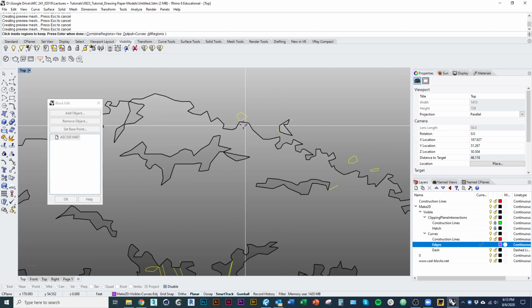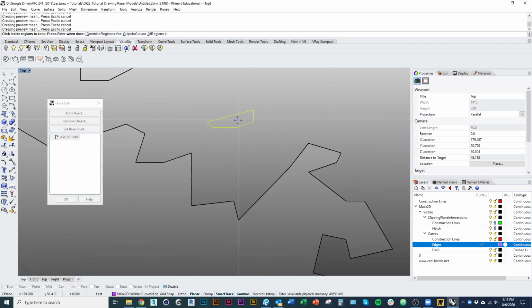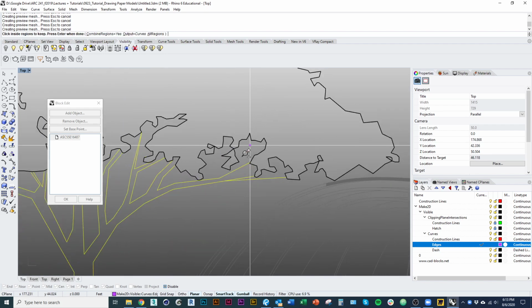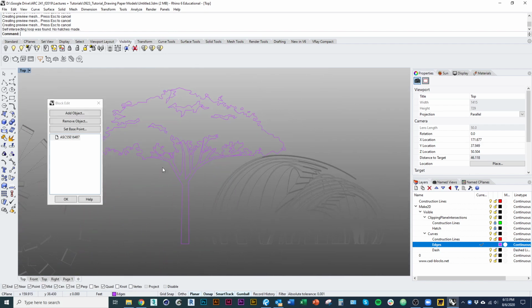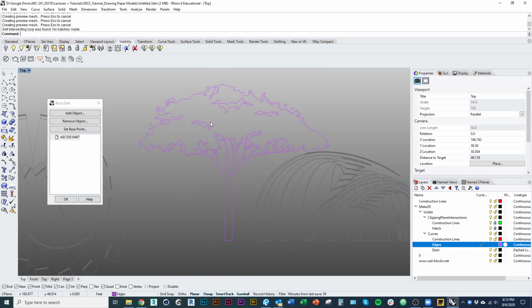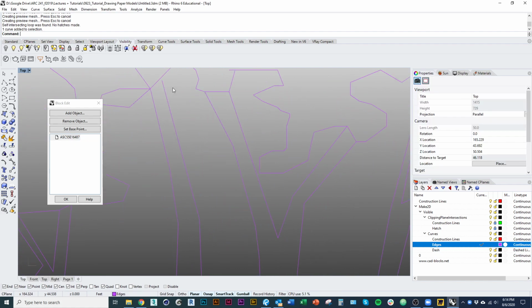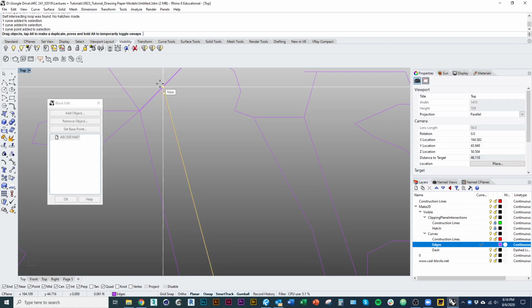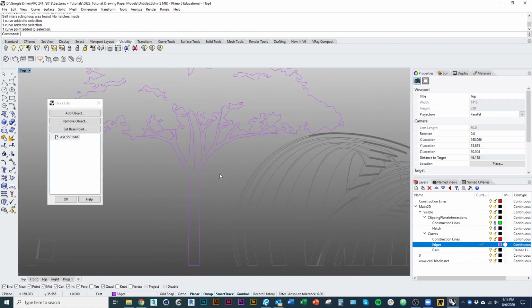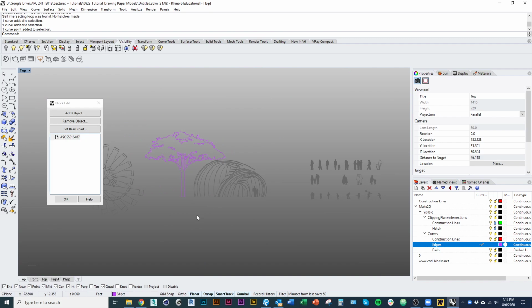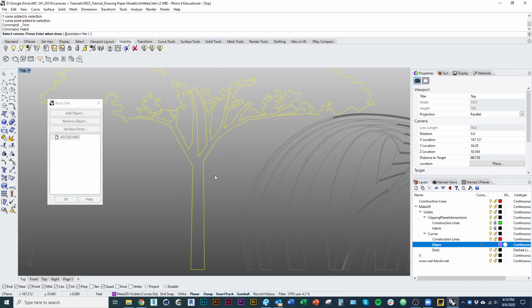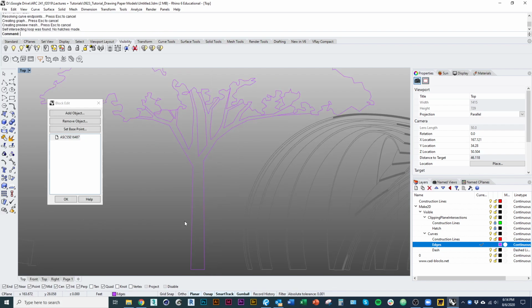Some of these other guys that are floating out in space. Okay. Enter. Oh, it says self-intersecting loop. So you kind of have to have relatively clean outlines to do this. And the other thing is, like here, for example, the reason it was filling that space in is because this wasn't a closed outline. There was a gap between the ends of those lines. Let's try it again here.